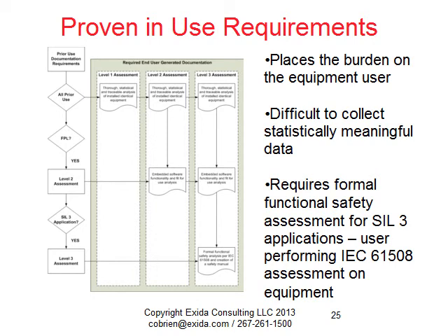So it puts the responsibility on the user of the equipment, and analyzers and detectors are going to have software, so you're at least at a level 2, so you've got to do a statistical hardware analysis, and you've got to do a fit for use analysis for the software. So that's a lot of responsibility for the end user. It is a path that's available. It's more practical probably if you're using a device such as a valve or an actuator where there's no software, and it becomes very difficult once you get into software-based products.